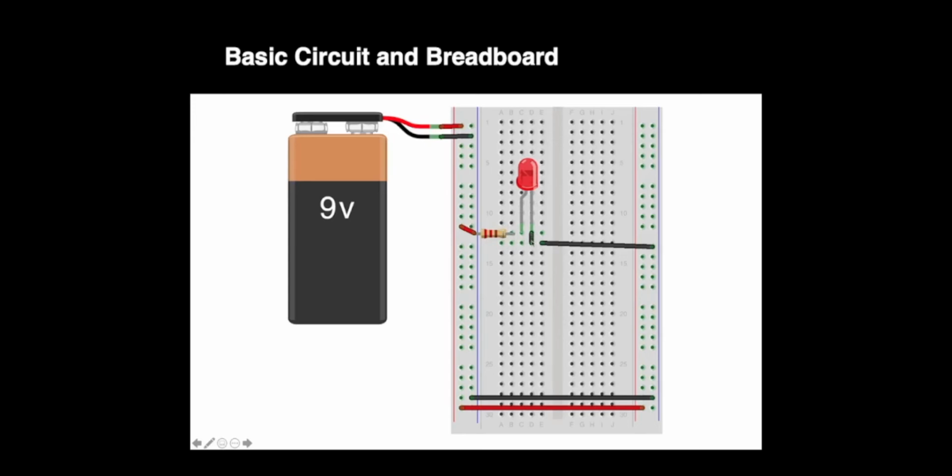It's kind of hard to see, but this black line is connecting that bit over there. So as long as these two leads aren't on the same row, that's really the only thing that matters. They have to be on separate rows. Otherwise, there's no break in between the circuit running through both leads. So that's why you have to separate the positive and negative side onto separate rows.